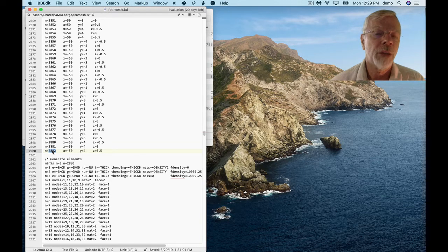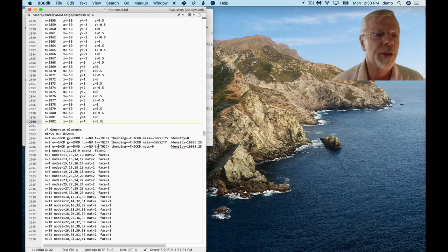Remember, the shell element we're using here is actually a macro element formed by 4 triangular elements in a cross-diagonal pattern. And the element internally will generate that internal node. And so there's actually going to be more nodes generated. This number plus the number of elements we have.